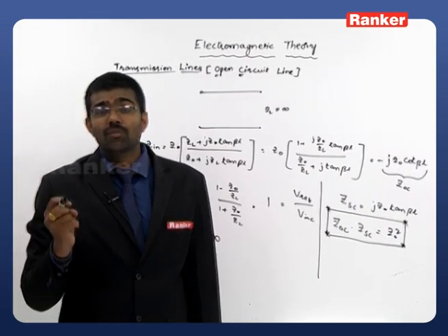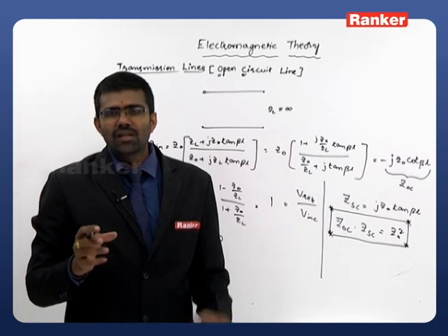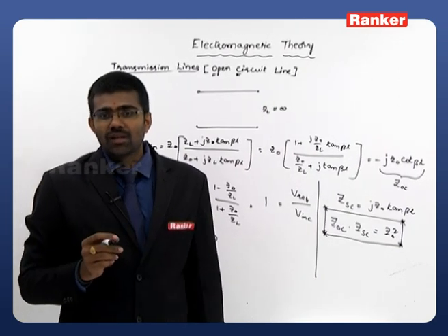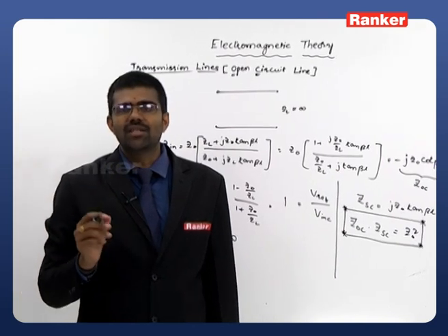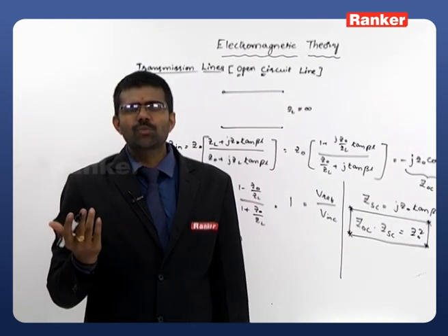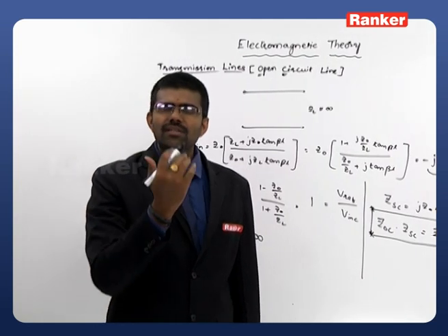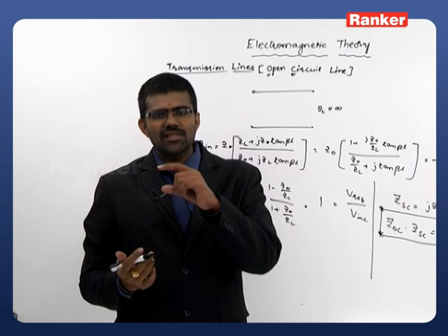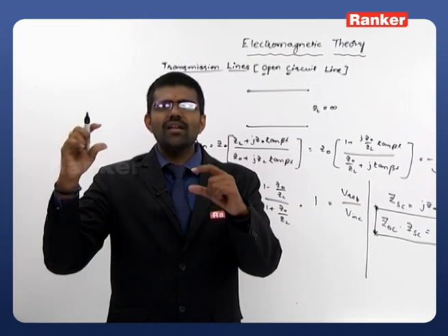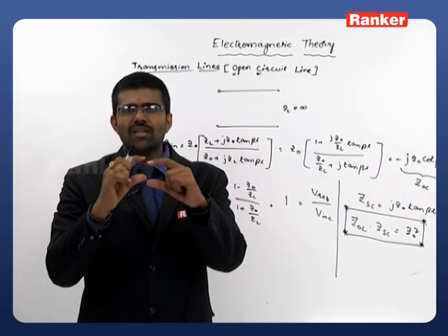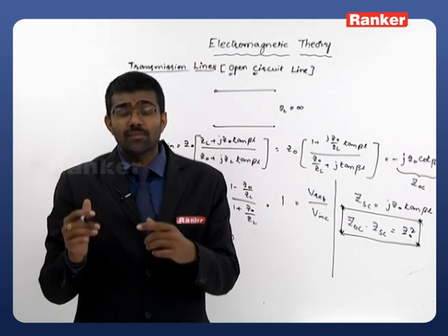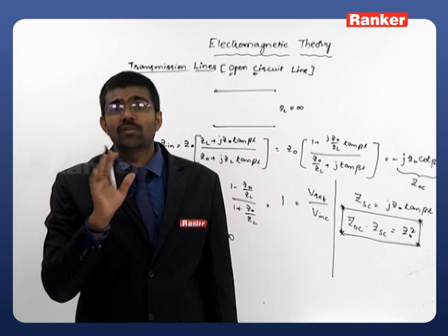Then if we require very good signal transmission, or if the signal is to be transmitted through the load, what is the condition? That case is called a matched impedance load. Matched impedance means the load is perfectly matched with the transmission line. The transmission line characteristic impedance is Z0, and the load I am considering is ZL. If these two are matching, then the maximum propagation must be there. That is our assumption. Now we will observe whether the propagation will be there or not.